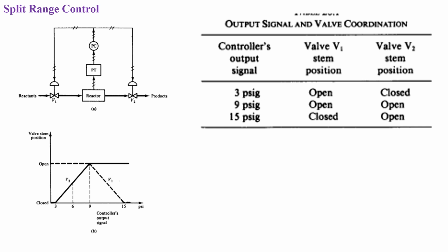Okay, and then in the cascade controller, there are two important inferences. Since there are two controllers introduced, the two controllers are always basic conventional controllers. So that's the number one takeaway point. Whether it is a primary or a secondary controller, inside it is based on conventional only, which is P or PI or PID.